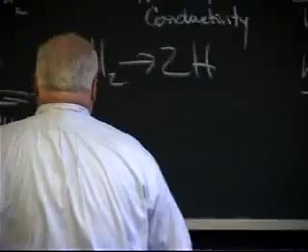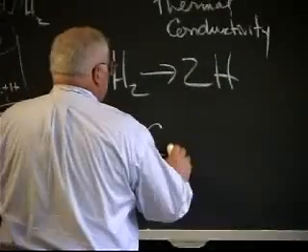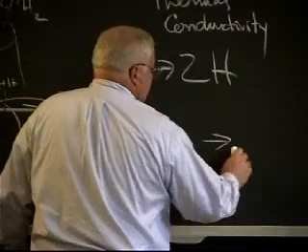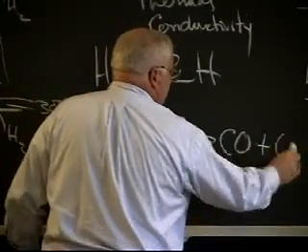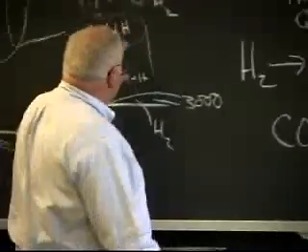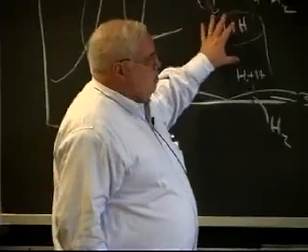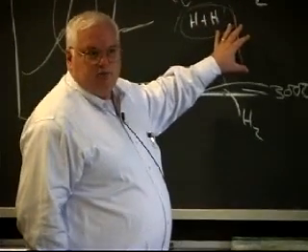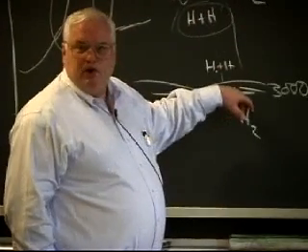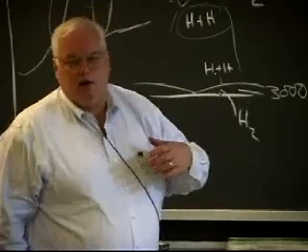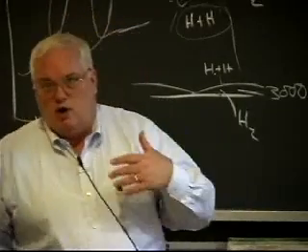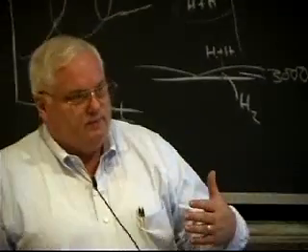But 5% hydrogen in argon will substantially increase the heat transfer to the surface. Now, it's not just hydrogen. If I weld with carbon dioxide, it will react in the plasma, dissociate up here to carbon monoxide and oxygen. And then down here it will recombine. So it turns out we actually do gas metal arc welding of steel with carbon dioxide.